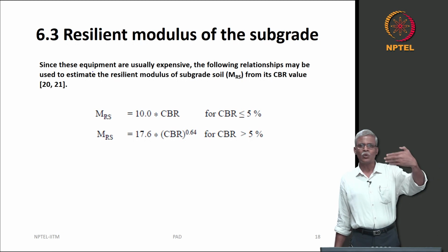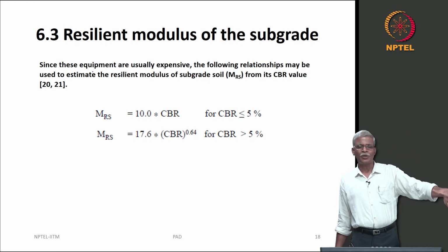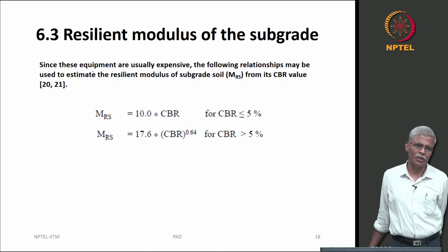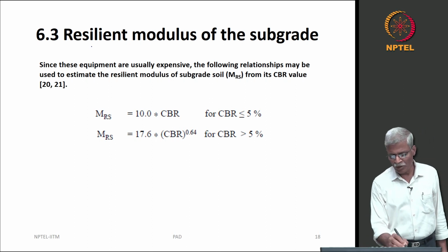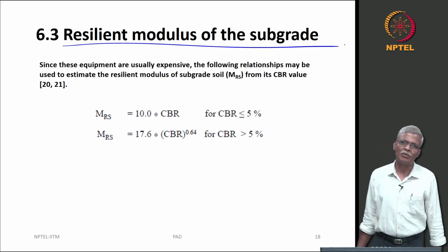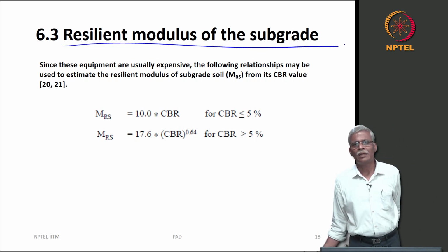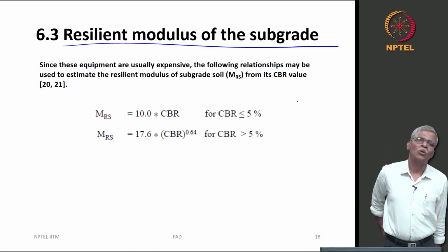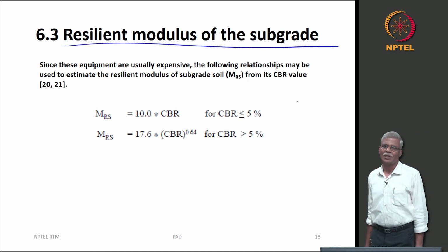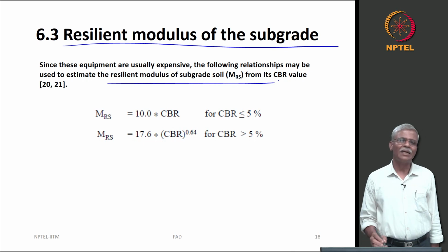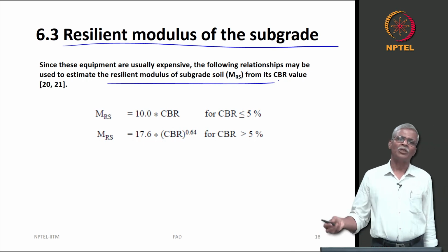Okay. So, now let us go through this stage by stage. What did you see? That was the distress part, distress equation. Now, let us start putting in the material properties. So, this is the resilient modulus of the subgrade. Now, what exactly is resilient modulus of granular material? You need to basically test it using the AASHTO T307 procedure. If you do not know how to measure it, just send me a mail and then I will explain to you.